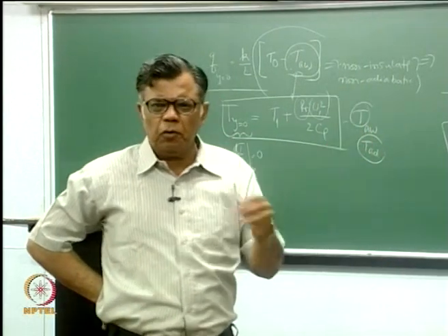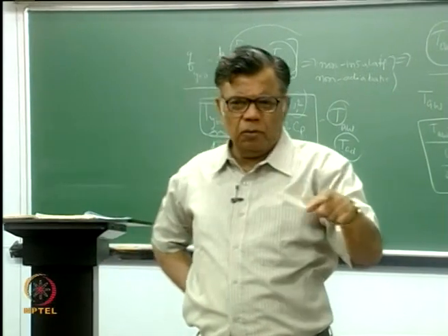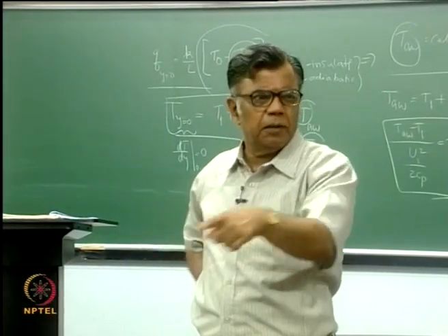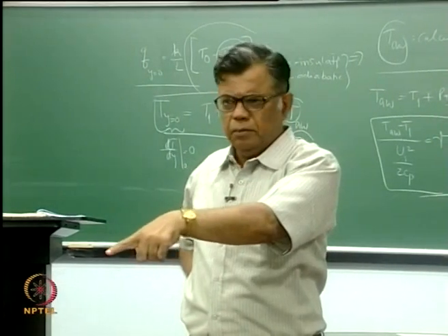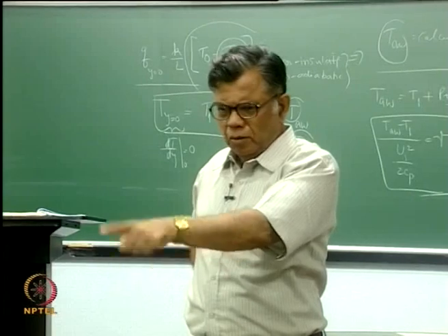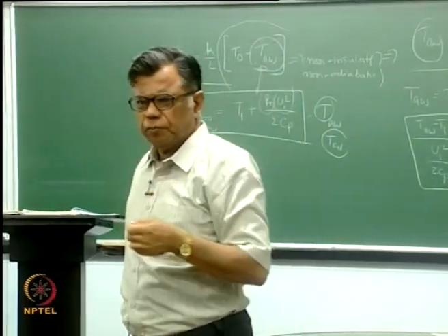So if you know the Prandtl number, half the solution is known. Now I do not know whether you have missed, for laminar boundary layer it should be Prandtl power half or something. Laminar high velocity, no you have missed it, it should be there somewhere, it should be square root of Prandtl number.